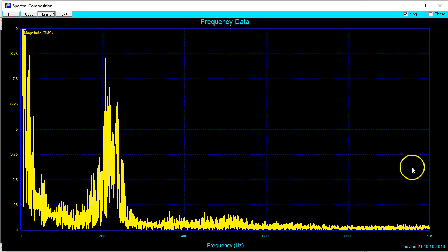Okay, and as we go forward to 4 kilohertz and 8 kilohertz, we're not going to suddenly find, whoa, there's a giant spike at 6 kilohertz. That's just not the way this is going to work. There's nothing on the copter that's going to make noise at 6 kilohertz. In fact, the higher the frequency we go, the weaker these signals are going to get. And so I really feel like when we get to 2 kilohertz, we're certainly starting to get to the point of diminishing returns, at least looking at the spectral data and from the perspective of aliasing and so forth.